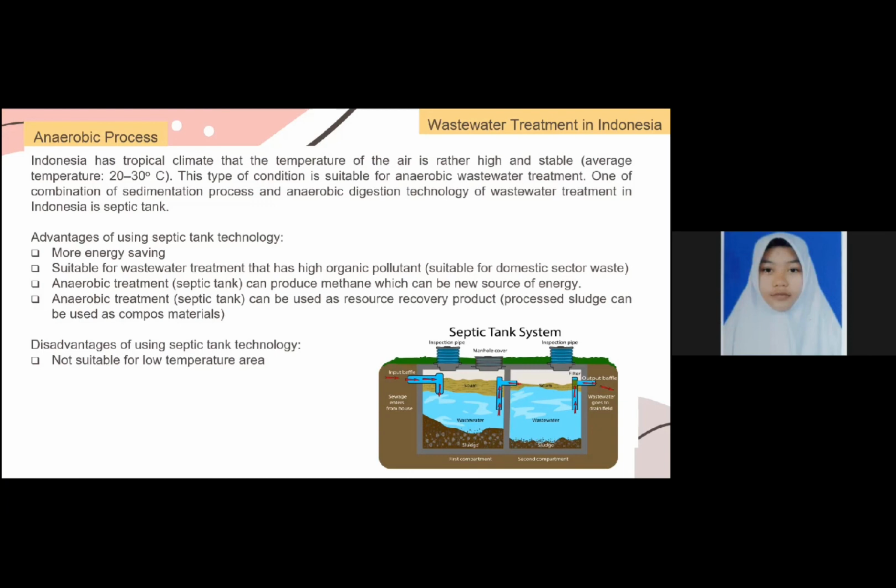The advantages of using septic tank technology are that it is more energy saving and suitable for wastewater with high organic pollutants, or domestic sector waste, since if the concentration of organic matter is low, the efficiency of an anaerobic process decreases. Anaerobic treatment or septic tank can produce methane, which can be a new source of energy. It can also be used for resource recovery, where process sludge can be used as decomposed material. The disadvantage of septic tank technology is that it is not suitable for low temperature.